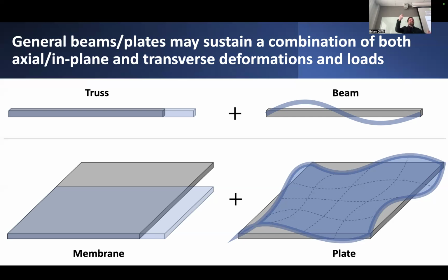And they deform only under these in-plane stretching deformations, resulting in these in-plane states of plane stress. So a membrane is basically equivalent to this two-dimensional thin plate type problem. So all the problems we solved in plane stress for these relatively thin plates were effectively membranes. They only experience these in-plane stresses undergoing in-plane deformations.